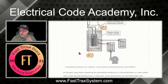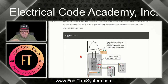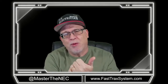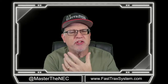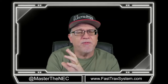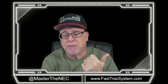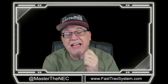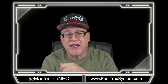And that's about as far as we're going to get when it comes to sizing the grounded conductors. Bring it back to me. So here, part 3 was a short one, but hopefully you watched part 1, got a little better understanding, high level view of what determines the neutral point and neutral conductor. You saw part 2, sizing that grounded conductor for practical application based on a load calculation for the maximum unbalanced neutral net current, and sizing for that, and then comparing it to 250.102(C)(1).